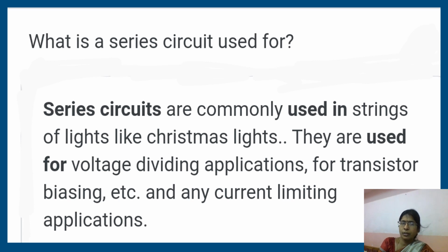Why is a series circuit used here? It is used for voltage dividing applications. You have seen that in a series circuit, across different resistors, it may be 2 or 3 resistors, the voltage is divided, like V is equal to V1 plus V2 plus V3. As it serves the purpose of dividing voltage, it is used for voltage dividing applications like transistor biasing, etc.